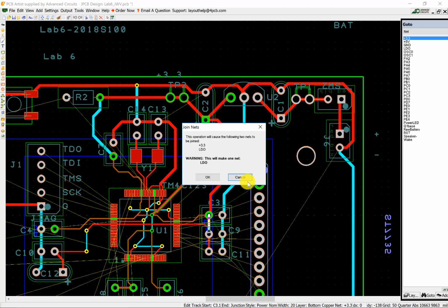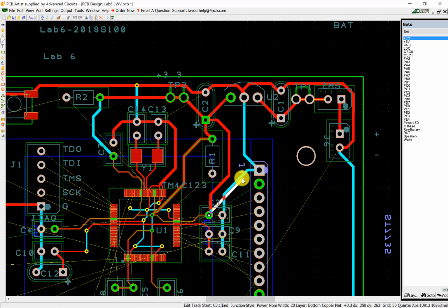LDO, here's something you know. Give me the 2 ways to reduce power in your system. You've got an embedded system on reduced power. 2 ways. Slow the clock down, get on the PLL, run at a megahertz, run at 500 kilohertz. What's the other way? And what's the relationship between power and bus speed? They want the equation.